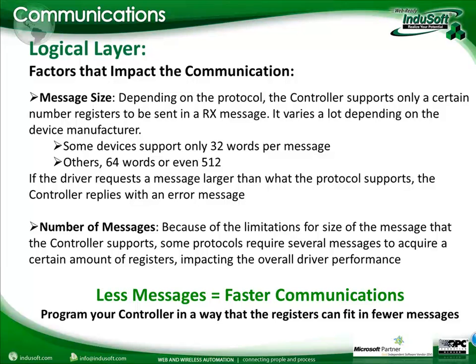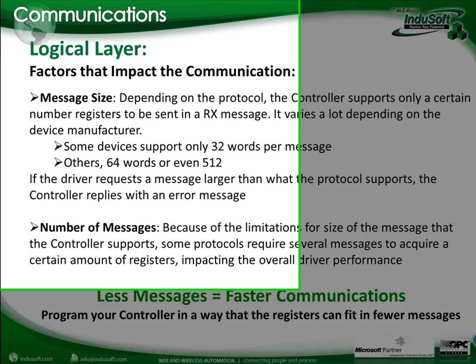Okay? Mainly on serial communications, you have smaller messages. For example, we have a Mitsubishi FX2 PLC. They support only 32 registers per message. If I request anything other than that, the PLC replies with a NAK, non-acknowledgement, and doesn't give me any data. Other devices support 64 words. You even have Modbus serial devices supporting up to 125 words in the same message.